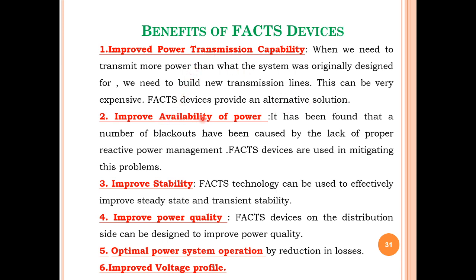Next point, improved availability of power. It has been found that a number of blackouts and power quality issues occur due to improper reactive power management. With a lack of reactive power management, we can see so many drawbacks. In order to compensate for the drawbacks, I would like to use a FACTS device. That is, it can mitigate the problems. Stability point of view: FACTS technology can be used to effectively improve the stability, steady state and transient stability. Remember transient, we can have some equal area criteria. If A2 is greater than A1, it is transient stability. If the disturbance is small, it is steady state stability.